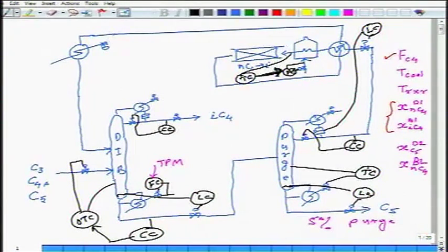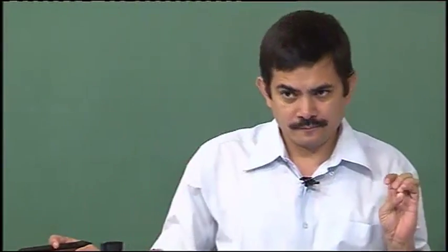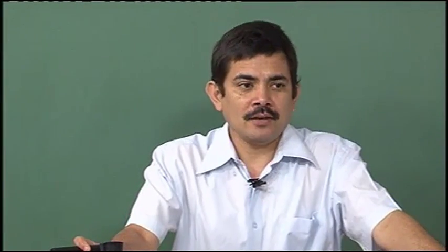Something similar here. Until the furnace is active, that is used as the TPM. Then until the boil up becomes active, that is used as the TPM. Then until the boil up in the deisobutanizer is active, that is used as the TPM. This allows you to have all three constraints active, no back off. Yes or no? Does that make sense? That is why I did what I did in that case.